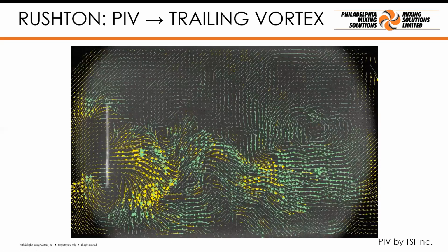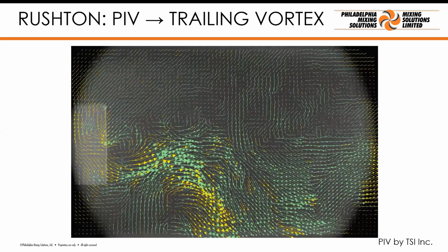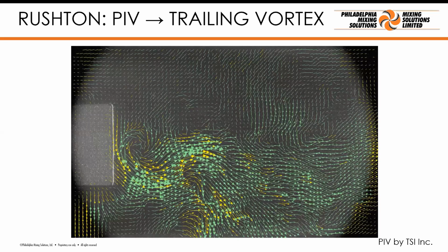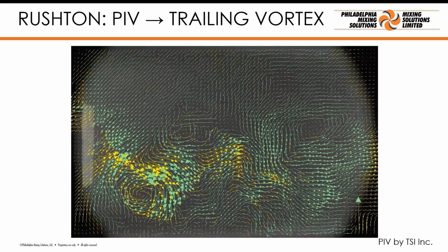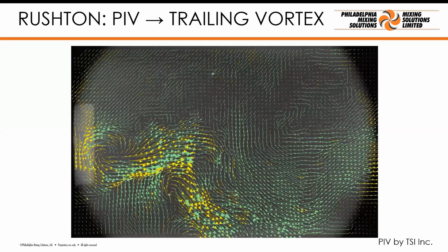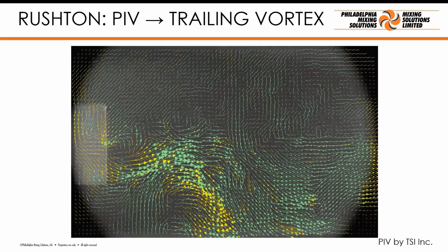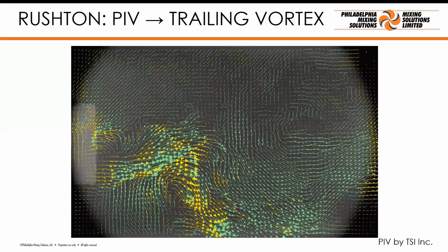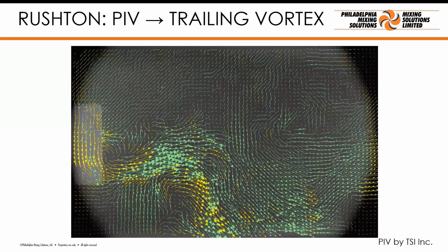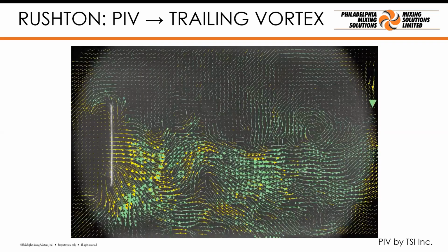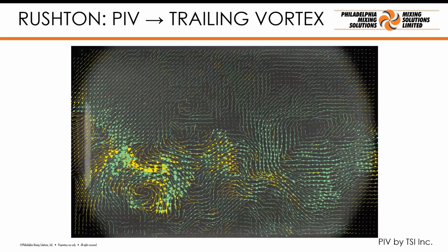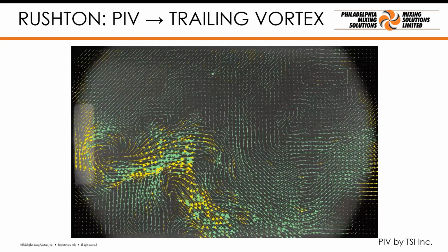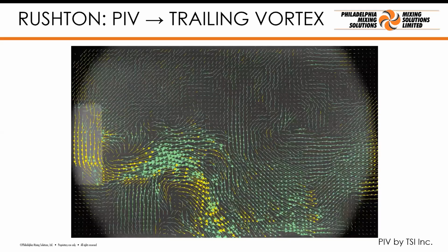This is the region in the tank where the local energy dissipation rate, the local power per mass, is a maximum. And this is the region where the drops are created. Once they're created, they move away. And as they come back, they may be broken up again. And eventually we get to an equilibrium drop size where the stresses pulling the drops apart are balanced by the resistance due to the viscosity of the drop and the interfacial tension.